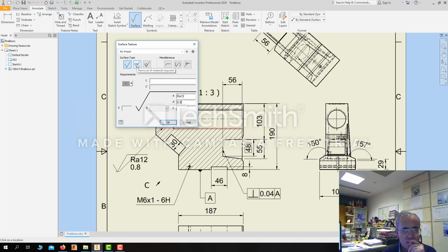Say that we finish the surface applying a material removal process. Select this. After saying that material removal is the process, in general, for finishing and setting the final quality of the surface, the machining allowance box will be active to write the allowance. In the example, the machining allowance is 0.5 millimeters, and the process is the honing process. Honed.